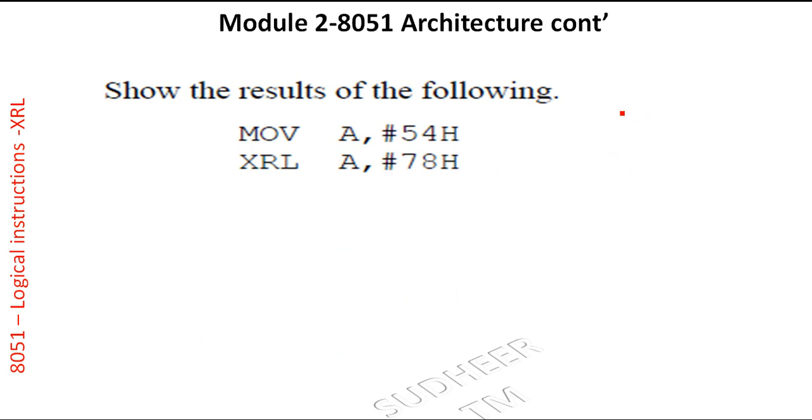So let us see the truth table of the exclusive OR gate. Say we have two inputs, X and Y, or A and B, whatever, and the output is X XOR Y. The possibilities are 0 0, 0 1, 1 0, 1 1. 0 XOR 0 is 0, 0 XOR 1 is 1, 1 XOR 0 is 1, 1 XOR 1 is 0. So this is the output for the different cases. Look at the output. The output is 1 whenever the inputs are different. The output is 0 whenever the inputs are the same. That is the logic. For different inputs, exclusive OR becomes 1. For the same input, exclusive OR is 0.